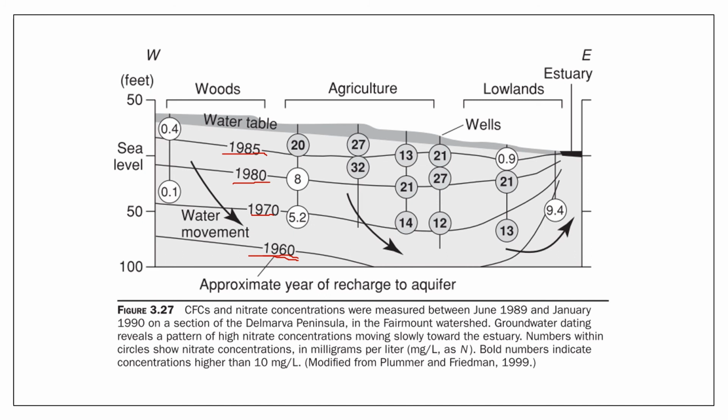So how that works is we just take the reference year here. This study was done in 1990, and at approximately 120 feet, we have water that is approximately 30 years old. All right, so it took 30 years for the whole hydrogeologic system to recharge the water at this depth. So this water is very difficult to replenish because it takes approximately 30 years to replenish that stock of water.